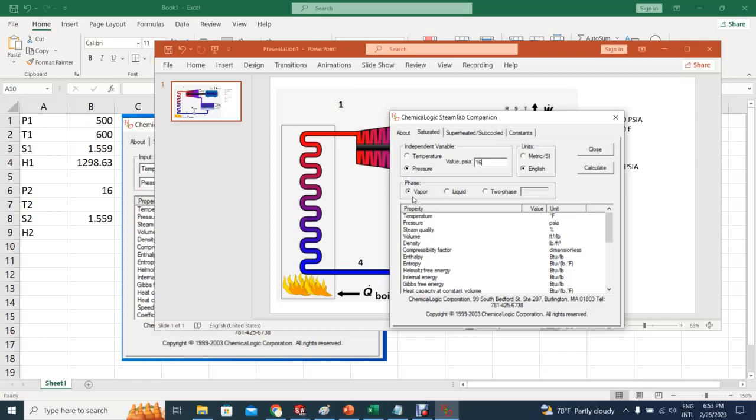The next thing, you leave that in vapor. When you hit the calculate, you check the entropy at that point is 1.74. It cannot be vapor, not at all, because I need a lower entropy, 1.559. You see what I need versus where it is, 1.74976, too high. This is not vapor. Would be liquid. Hit liquid. Calculate again. When you check on liquid, entropy 0.318, too low, cannot be liquid. Now you know. Well, if it's not vapor, if it's not liquid, definitely it's a two-phase system.